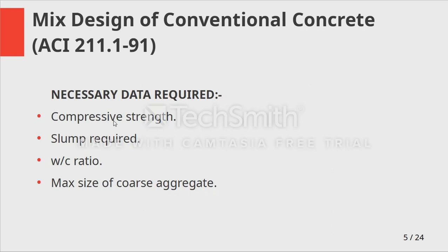So you need compressive strength. How much compressive strength do you need to achieve? What is the requirement of workability? How much slump do you require on a site? What is the water to cement ratio?